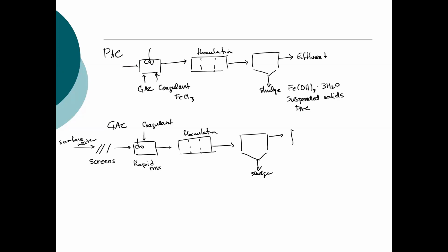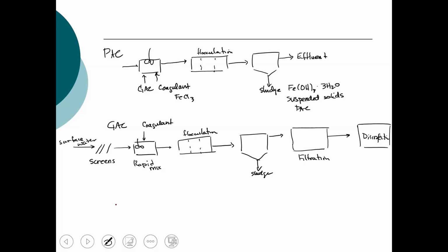Exactly, filtration. And I added the screens before, so we have filtration. And then following filtration, we typically have disinfection. Where are we likely to add the granular activated carbon? There's two places. One is right here. So we can actually add carbon to the filters.